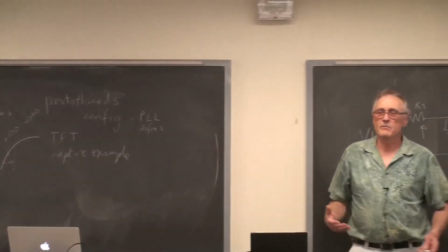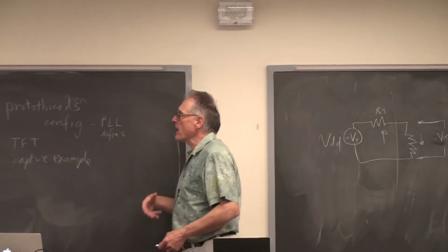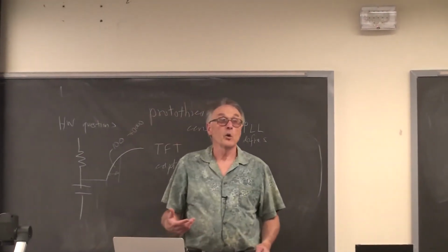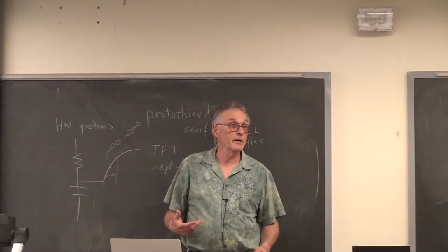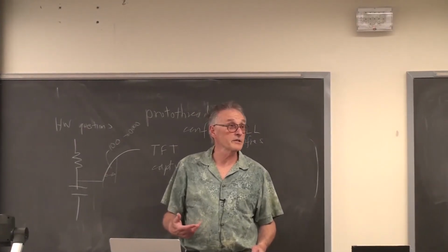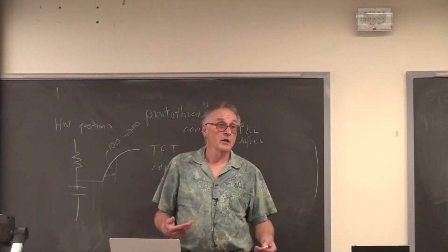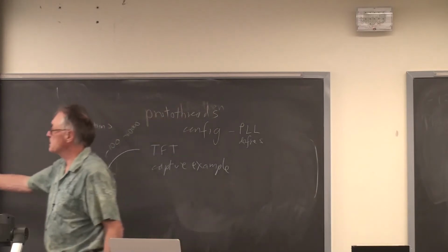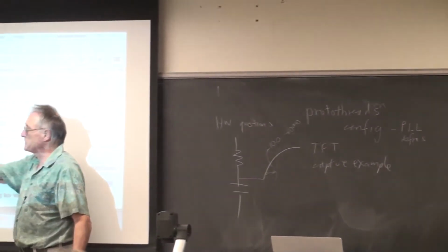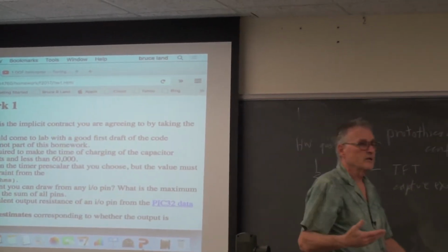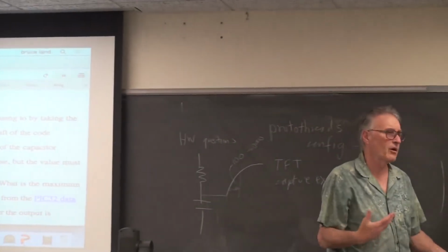I would guess that the one problem with very high values of resistance is you start getting noise because you're picking up EMI, electromagnetic interference, from other parts of the circuit. The higher the resistance, the more EMI. So you have a lower bound, which is defined by the accuracy of the discharge, and you have an upper bound defined by EMI to be 1 or 2 or 5 megohms or so.